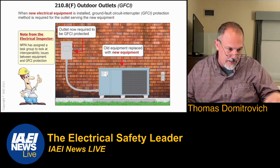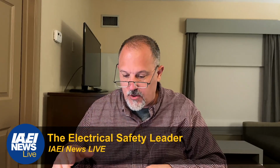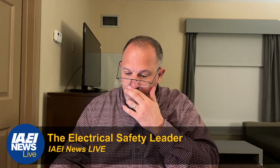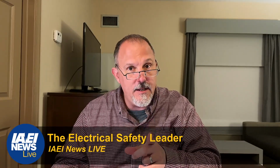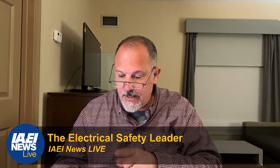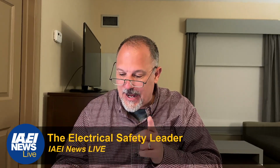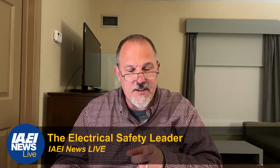Oh, and the other thing that we did. So in addition to the dwelling unit outdoor circuits, we added garages that have floors located at or below grade level. We added accessory buildings and boathouses. So we expanded the GFCI requirements for outdoor circuits. Now, we also added text that says if equipment supplied by an outlet covered under the requirements of this section is replaced, the outlet shall be supplied with GFCI protection.